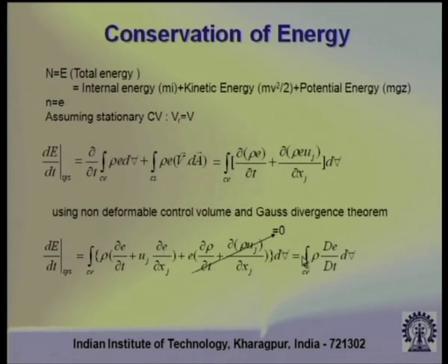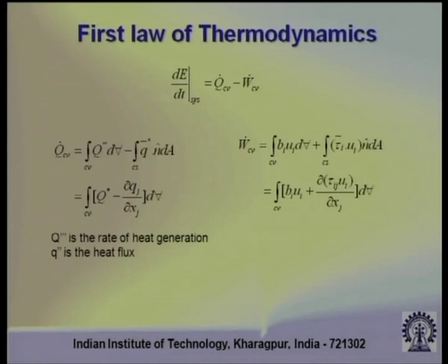With this understanding, it is now important for us to express the left hand side. See why we have done all this. The right hand side gives the rate of change with respect to time plus the rate of change with respect to position as you see it across a control volume. The left hand side talks about the same thing for a system. So, for the corresponding expression for a system, we can use the first law of thermodynamics, and for that we go to the next slide.